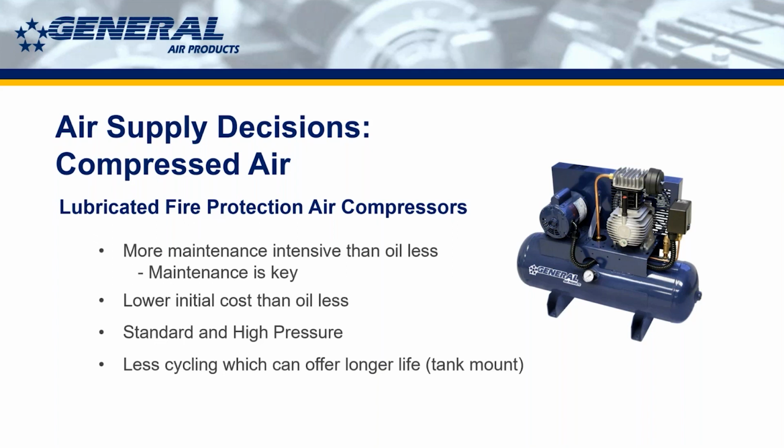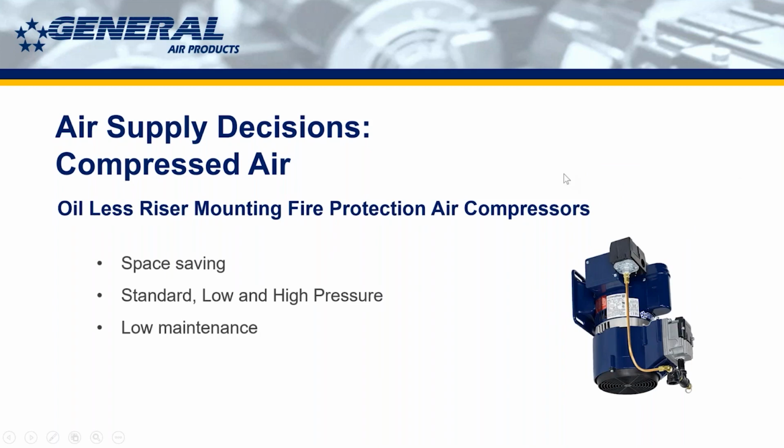Also making sure that the tank doesn't fill up with water, because when you compress air, you get water, and it collects in the tank. So somebody's got to drain that. If somebody's doing all that, a lubricated compressor is a great way to go. If no one's going to be on site to do that, then an oilless compressor is more the way to go. That's offered in two styles, tank mounted, and what you're looking at here is a riser mounted oilless air compressor.